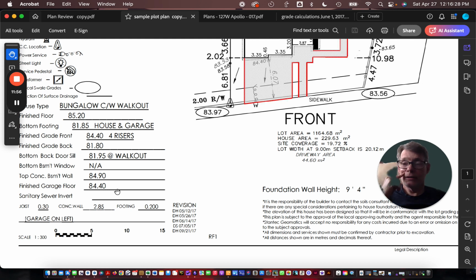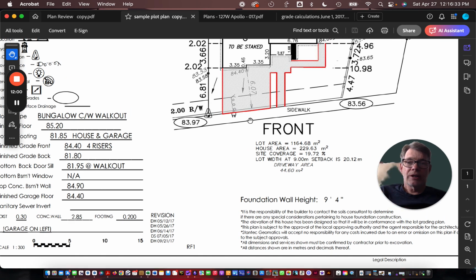You and your builder are going to have to be just mentally alert here, because one of the first things that will happen is we're going to discover where that sewer is, and we are going to hope that it's deep enough to accommodate the slope that we need. Now, you're building on a slab, you live in Arizona, they don't do basements, you are not going to have a problem. Your sewer is going to be whatever, I don't know how deep they go in Arizona, 4 or 5 feet, something like that. It's going to be easy. Life is so easy when you have no frost and no basements. Here in the frozen north, less fun.